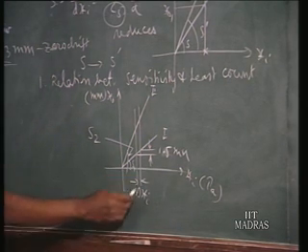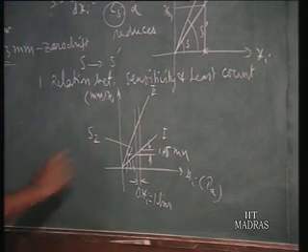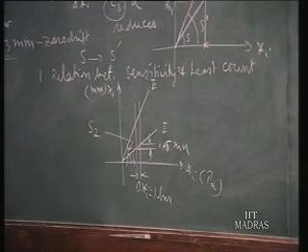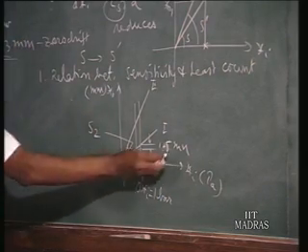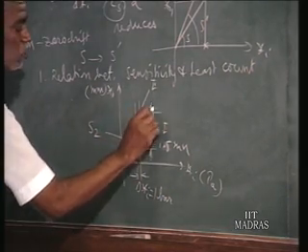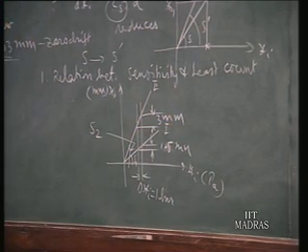So, for the first instrument, for a delta xi, may be 1 bar. For a 1 bar change, the first instrument gives a displacement of the pointer in its scale to an extent of 1.5 mm. The second instrument deflects to a distance of say 3 mm.